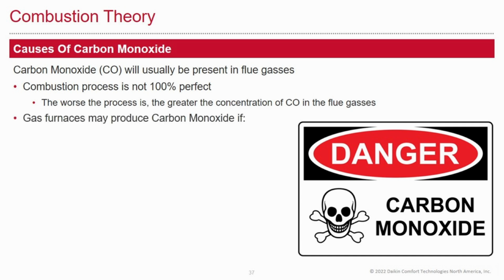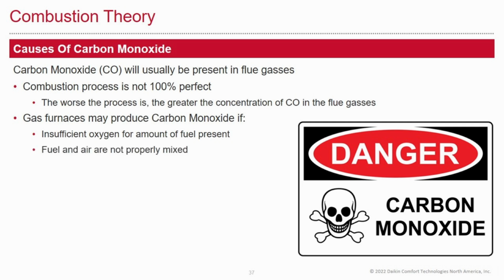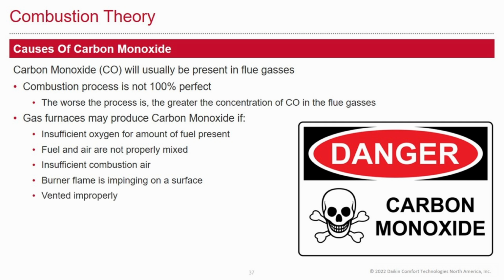Gas furnaces may produce carbon monoxide if you have insufficient oxygen for the amount of fuel that's present, the fuel and air are not properly mixed, you have insufficient combustion air, the burner flame is impinging on a surface, it's not vented properly, or there's a crack in the heat exchanger that prevents complete combustion.